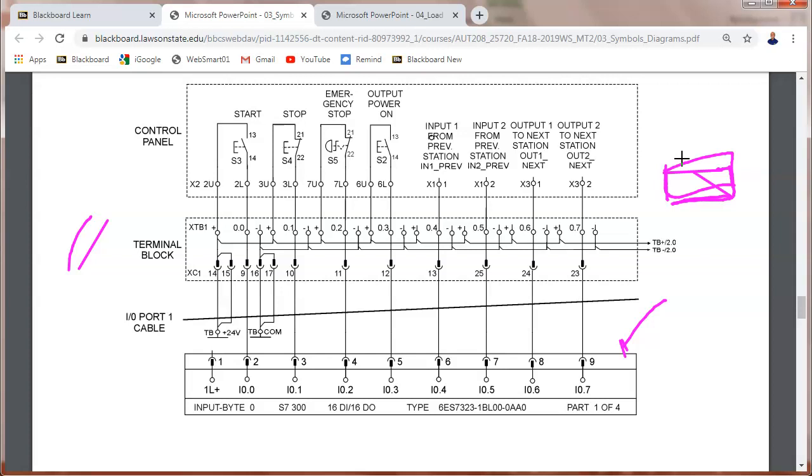But with most of your newer PLCs, where you hook up to the I/O on the PLC, the terminal strips actually snap off. There's two screws on the outside. You can unscrew them and snap them off, and that way you don't have to do any rewiring to replace the PLC. You just pop the terminal strips off, put the new PLC in there, download the programs into it, and put them back up. That's how most of the new ones work, to make it real fast to change them out.